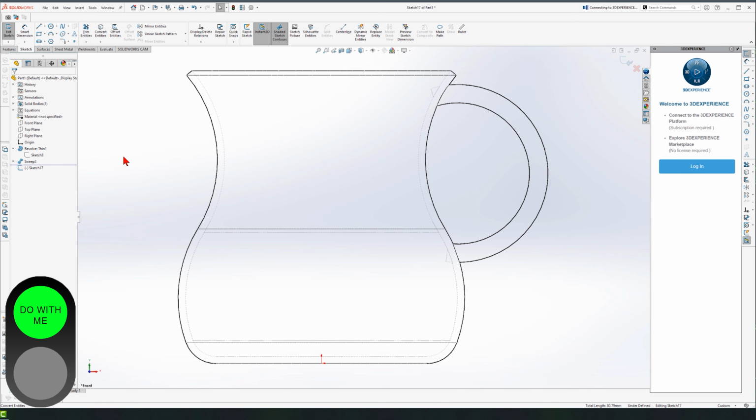This is a good example of being able to follow tutorials, but not being able to model something on your own. Because if this was an edited video, like all the other YouTube videos teaching SolidWorks, I would cut this place out and do it with the next method, show you. But next time you go ahead and model it on your own and you face this issue, you don't know who to ask and why this is happening to you. So this is not allowing me to convert this inner line into a sketch, so I can use a negative revolve to get rid of these two sharp points that are sticking in. What do we do?